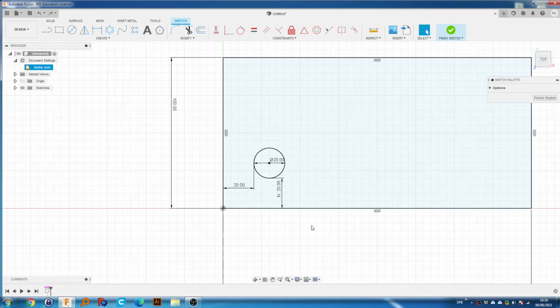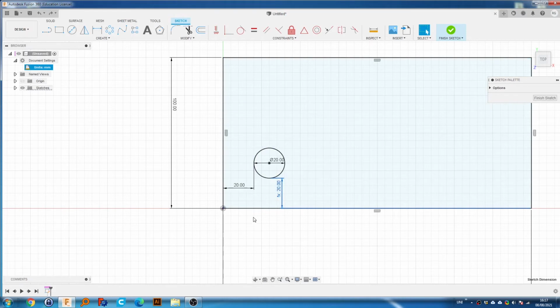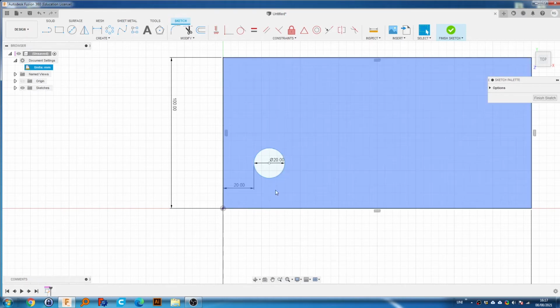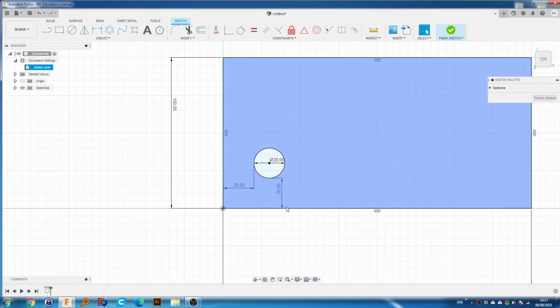Just like that. So another way we can do it is to define it. Say we get rid of that dimension. Actually, let's go back. Instead of typing D6, we could type in a parameter, and then we could use our own parameter name in the future whenever we like. So we could type in wall dist or something equals 20.